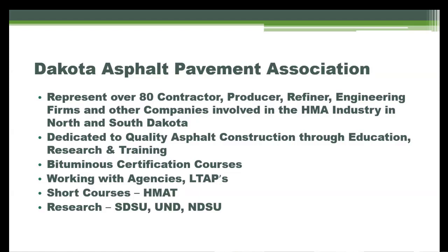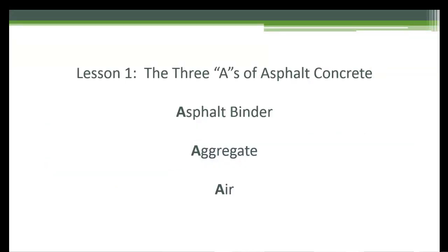Going to the three A's, we talked about two of them already, the asphalt binder and the aggregate. The third one is air, and I want you to think of air as what we look at for mix control and mix design in the asphalt world: air voids. You've probably heard that before. And we design and control to that in the field. So air is really representative of the mix design itself.